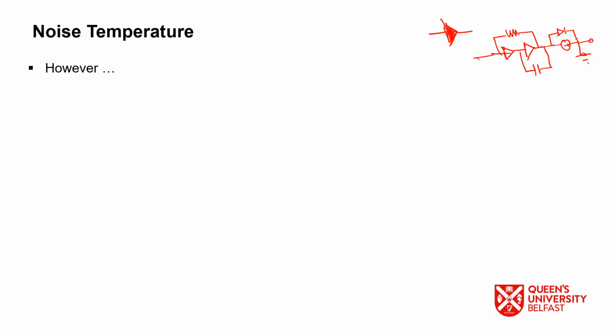So what we normally do is place this whole system into a black box and calculate what exact TE is, and then consider that TE as the equivalent noise temperature, and we are only then worried about what gain value this system will give us.